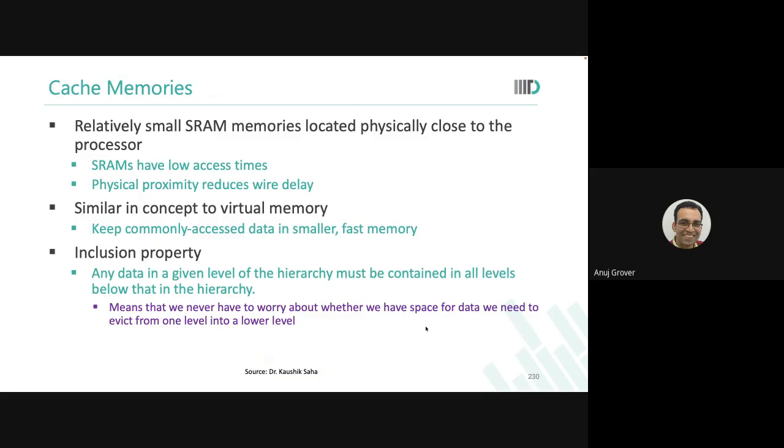Yes, in many server grade systems, embedded DRAMs are used as level 3 caches. Because DRAM is anyway not as fast as an SRAM, whatever you may do. But you can still use it as a cache, and in many server class systems, they are used.